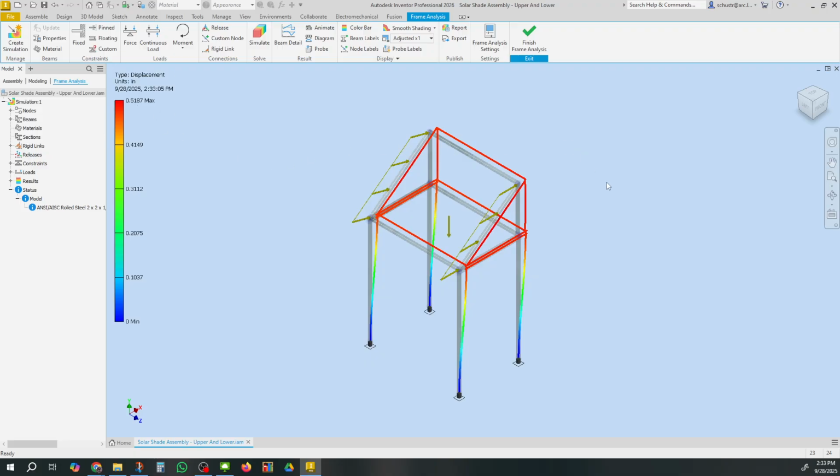It doesn't tell me, see what I can get out of my diagram. It gives me forces, stresses, displacement. It doesn't give me a safety factor. Okay, but I can find stresses if I want. Max, min, I'll look at my max. It's pretty low. It's pretty low. So stress-wise, I'm probably okay with this, but it's wobbling too much, even though it's got not that much stress. Okay, so this is how we would use it.